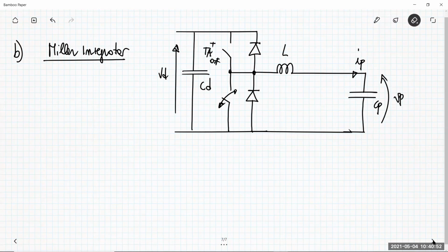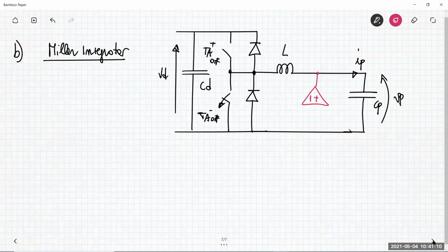So I have to put all the transistors off, and I have to find out another means to dissipate the energy that can be no more recovered. So now the circuit is a Miller integrator. Let me put here an operational amplifier with a capacitor in its feedback.